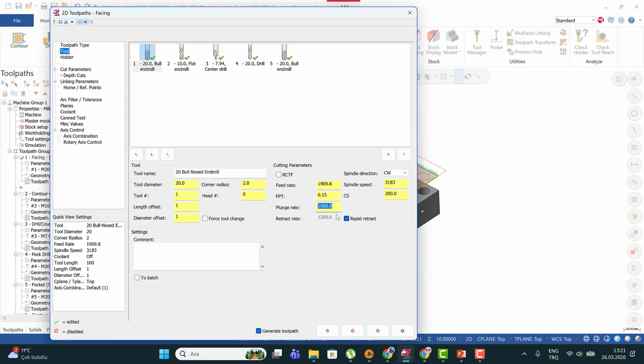I can also say that feed rate is calculated from different perspectives. For example, according to your toolpath geometry, if you have a sharp corner in your toolpath geometry, you cannot use a higher feed rate. Another perspective is your chip thickness.